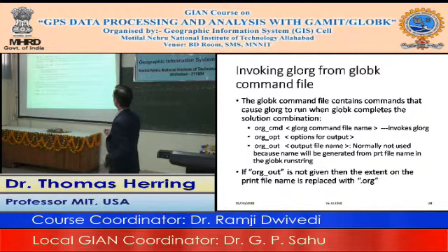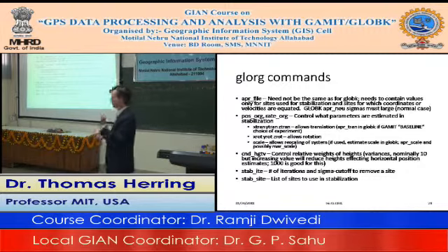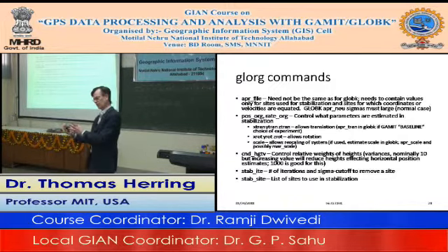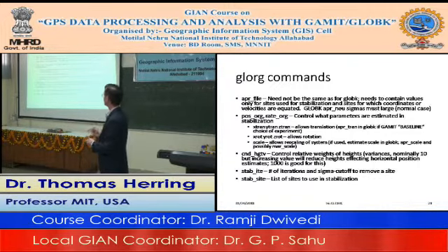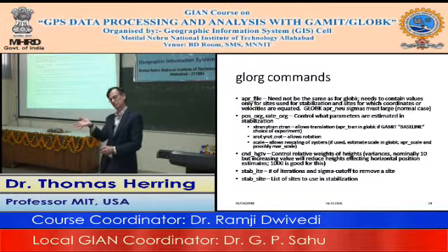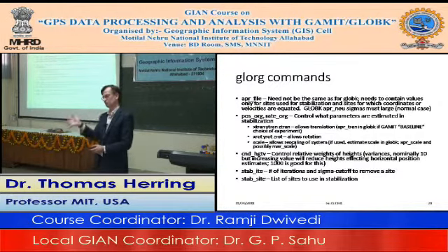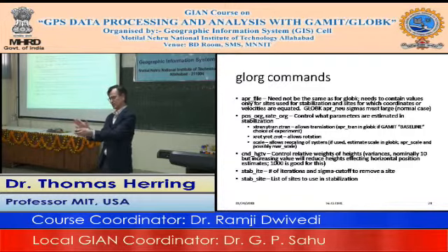Okay, so the APR file, the coordinate file, which you can also specify in GLOG, does not need to be the same as you used in GLOBK. And this is a very powerful feature because often when we run GLOBK, we will run it with just the standard ITRF, no net rotation coordinate system. But then when we want to run GLOG, we want to do our frame realization in, say, the Eurasian reference frame. So we will give it an APR coordinate file in which the velocities are in the Eurasian reference frame. And that way we can do our reference frame stabilization or realization in Eurasia, not in the other frame as we go across.